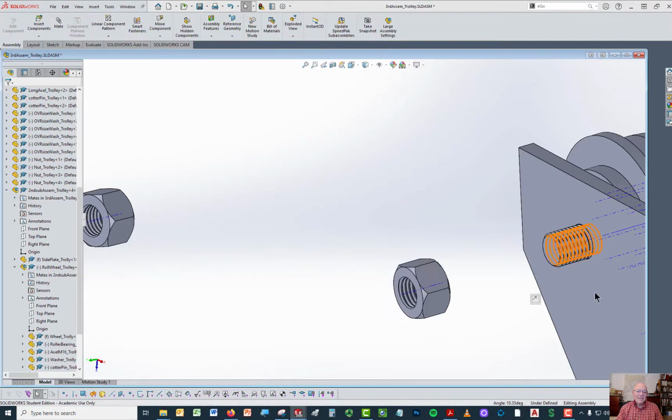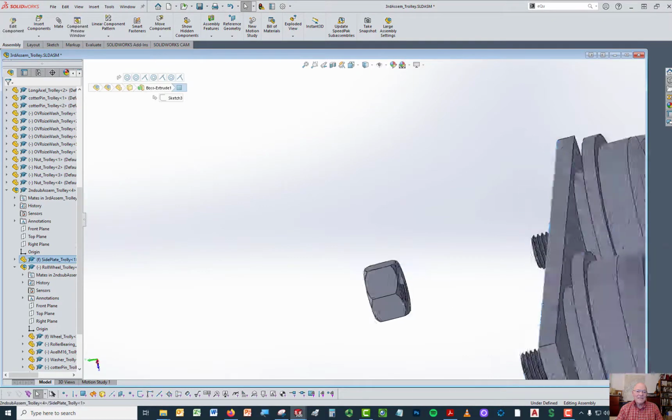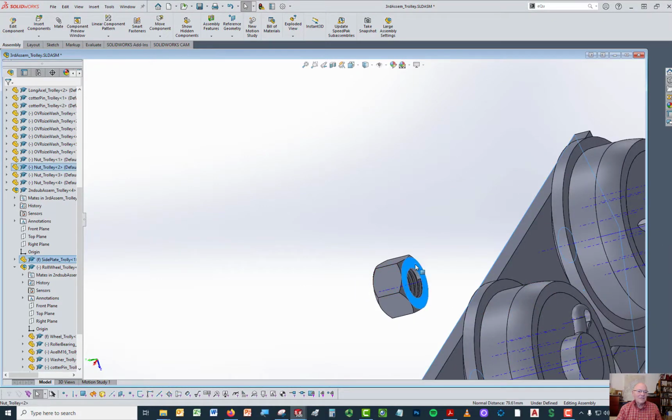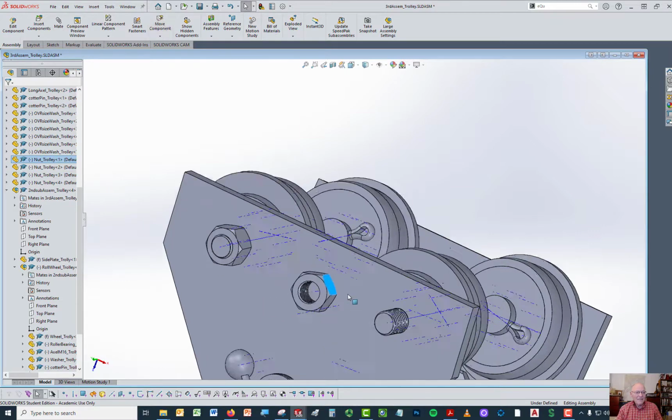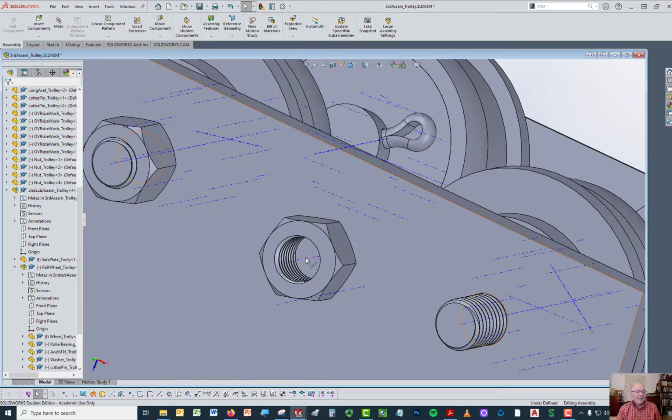Now it comes in like this. Then make that surface and that surface coincident. Now the nut's on there and it's centered, so you aren't going to have, oh, I see. That's probably why they had an interference before, is because they tried doing concentric and that didn't work. They did something else. But again, I'll take the axis of this, the axis of that, make them coincident.